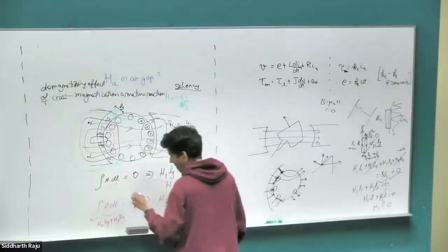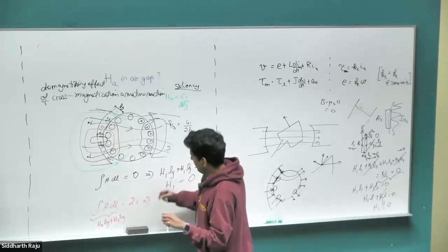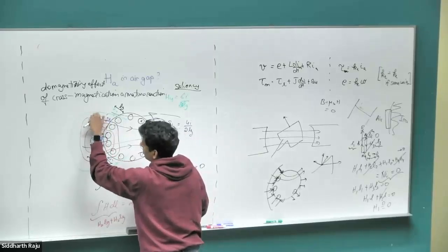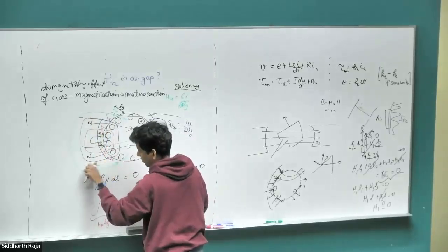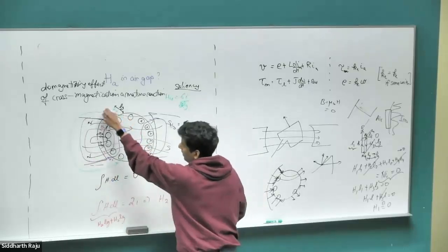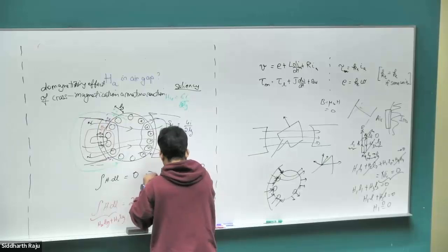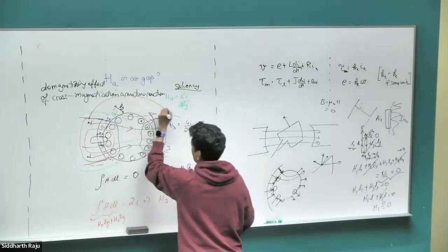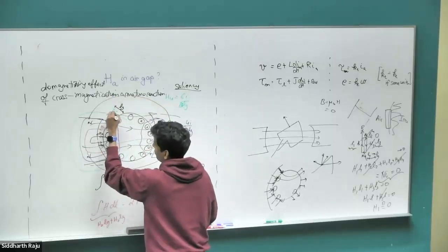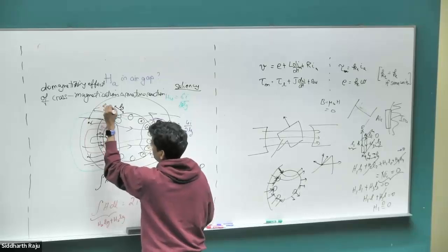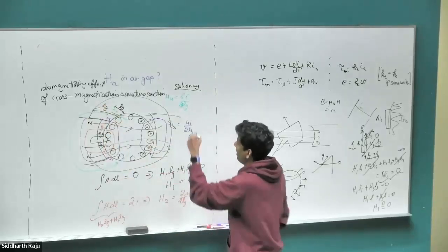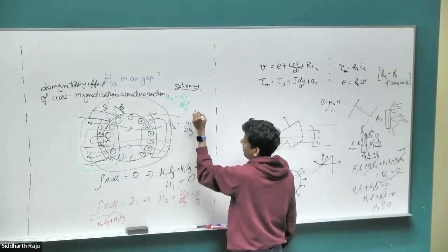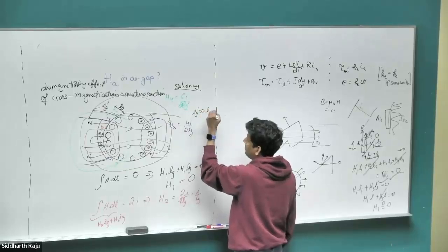So going back to our equation, when you solve this, these would have been the same H1, H2, H3. But if you look at the H4 pathway, the magnet has now reduced. Right? Now, the H4 pathway is going to have to take a much, much longer pathway to go to the stator core. So let's say we have a stator core surrounding the structure. The LG length for the H4 pathway has increased significantly. Right? So this would not have been the same LG as before. This would have been a new LG, LG prime. LG prime is much, much greater than LG.